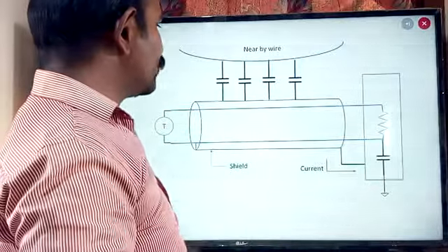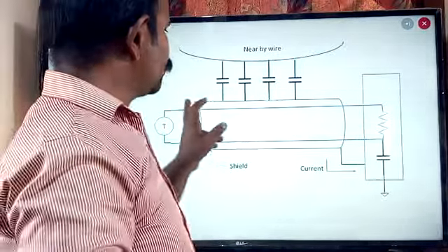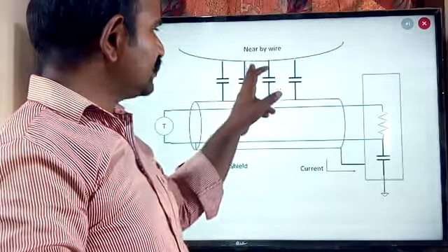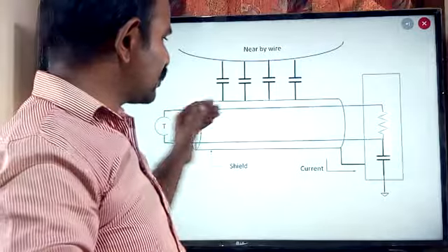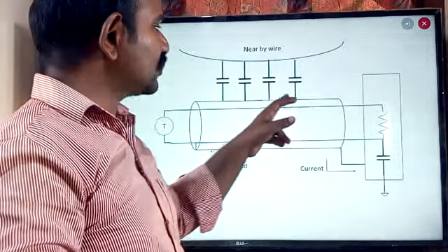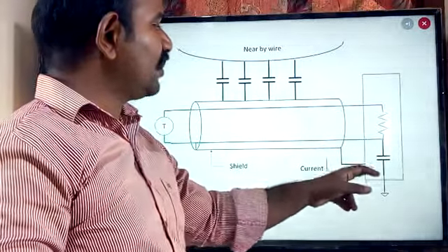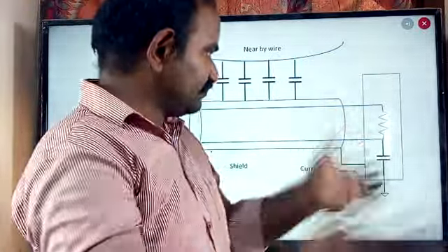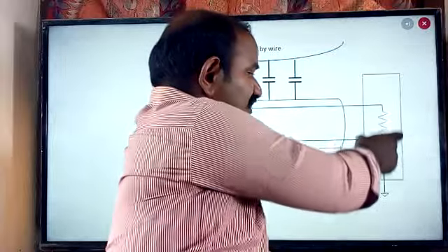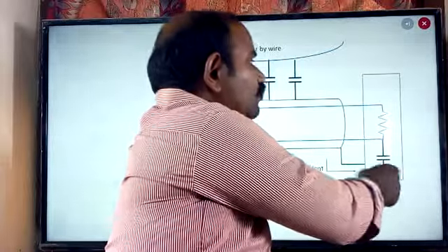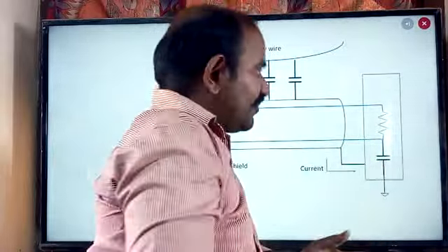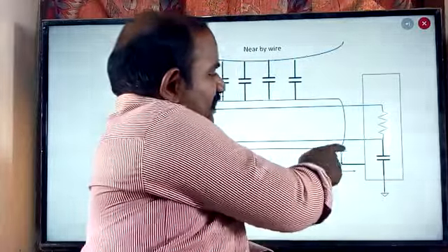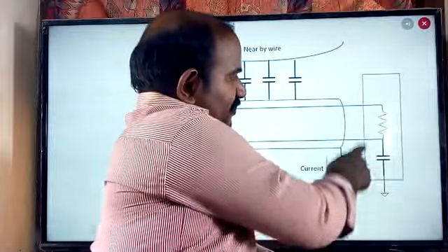So because of that, what we are going to do is use the jacket now. This jacket is connected to the ground. Whatever noisy signals are trying to induce into our communication path are going to be bypassed to the ground via the device box. We are having the device now. The body of the device is going to be connected to the ground, and this wire is going to be connected to this particular body, the device body.